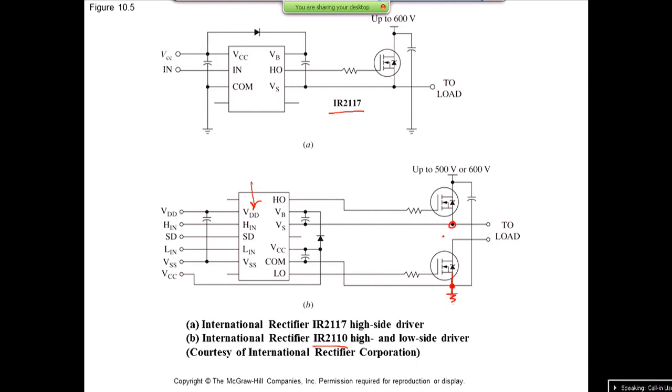Imagine you want to try to build like a half bridge kind of a circuit. You have two transistors. One of them is grounded, no problem. A low side gate drive would do it. The other one is not grounded, so you need to have a high side driver. So there are solutions out there you can just purchase, and it's very, very important to have these caps over here. Do not just neglect them because they are very, very fundamental in the operation of the converter, of the gate driver. All right, so this is all about a little bit about gate drivers.